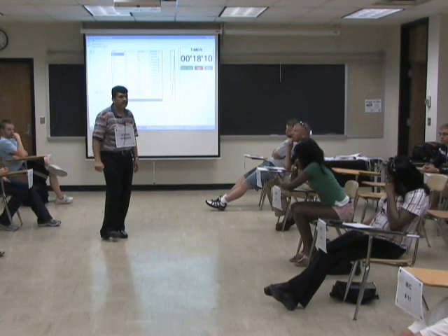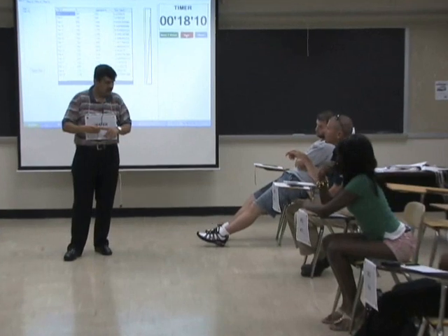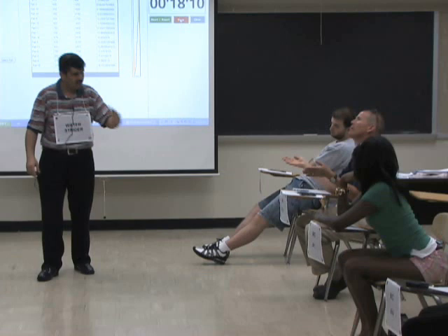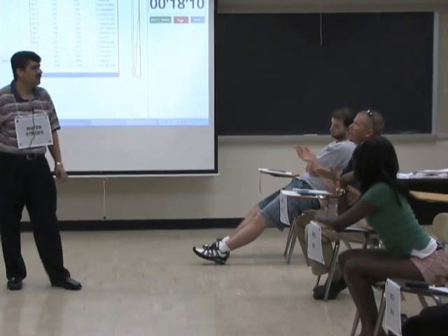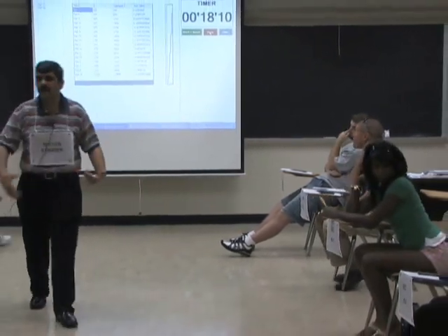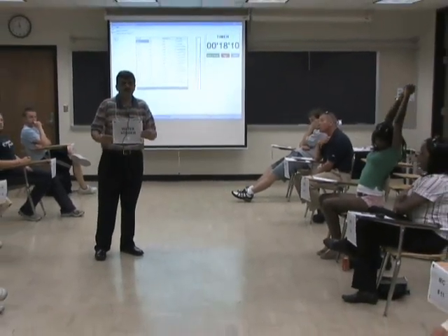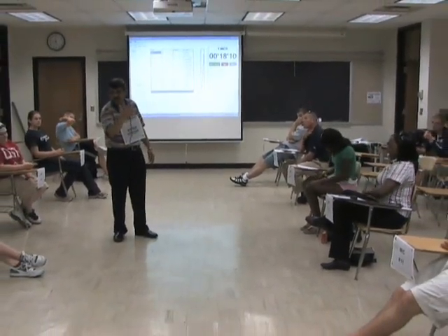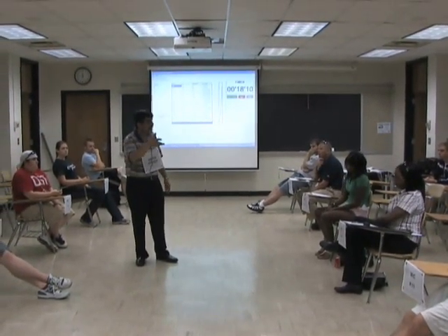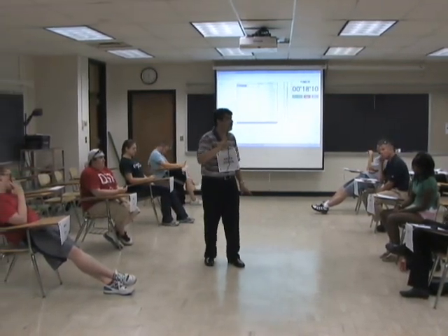Any other observations? In this simulation, you pretty much ran the factory dry. If you had to start up another shift, or at the end of the month, the first of the month typically, now you have people waiting to get the jobs in the system. So the question to you might be, you may have observed some of the work which was being done. One thought is, could you combine machines? For example, you could take machines 3, 5, and 2, because they're used consecutively, because they're lightly loaded, you could potentially group them into a small 3-machine work cell and have one person run them.